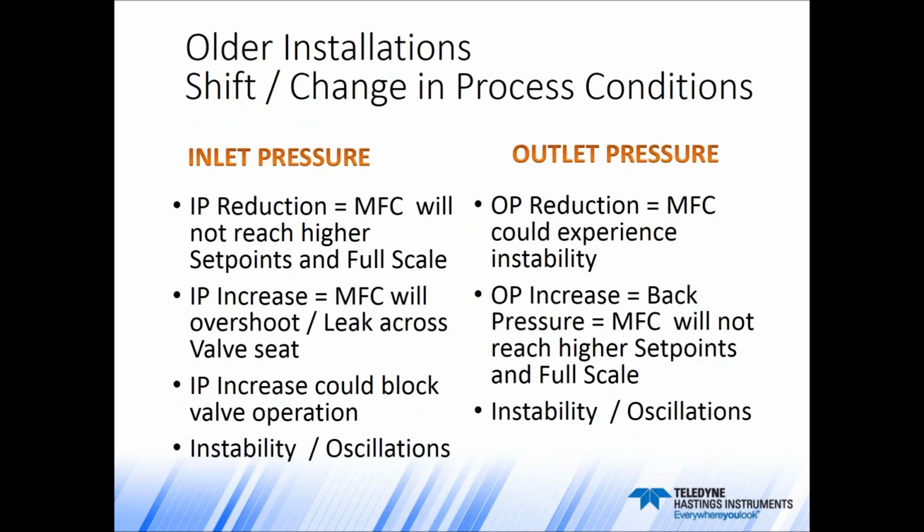So let's look at some of these influencers of the MFC performance. And we start by talking about pressures. Doug has pointed out how important working with the inlet pressure and outlet pressure in new installations is, and how critical the sizing of the flow controller is based on this inlet and outlet pressure. Teledyne does a great job at marking the pressures on the label of every single flow controller that is being produced, and we replicate that on the flow controllers that are being serviced. So inlet pressure and outlet pressure will affect the behavior of the flow controller.